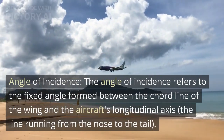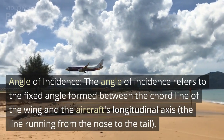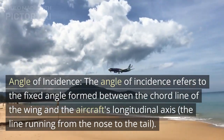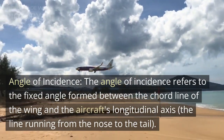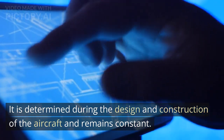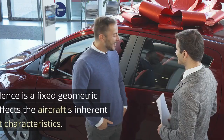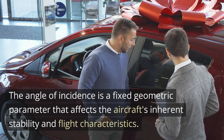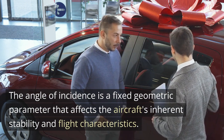Angle of incidence. The angle of incidence refers to the fixed angle formed between the chord line of the wing and the aircraft's longitudinal axis, the line running from the nose to the tail. It is determined during the design and construction of the aircraft and remains constant. The angle of incidence is a fixed geometric parameter that affects the aircraft's inherent stability and flight characteristics.